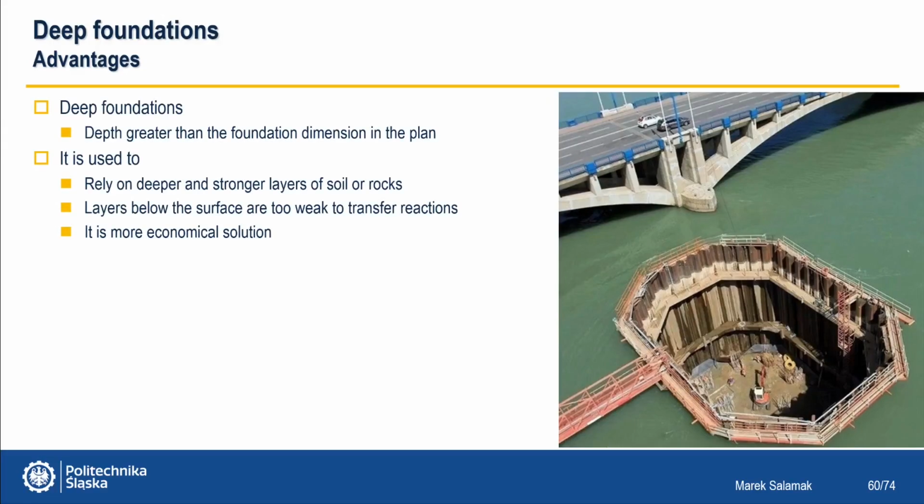However, deep foundations are used much more often in bridges. The depth of such a foundation is already greater than the foundation dimension in the plan. They are used to lean on deeper and stronger layers of soil or even on rocks. The layers below the surface are usually too weak to carry the reaction, or it is simply a more economical solution because deep foundations usually cover a smaller area than a